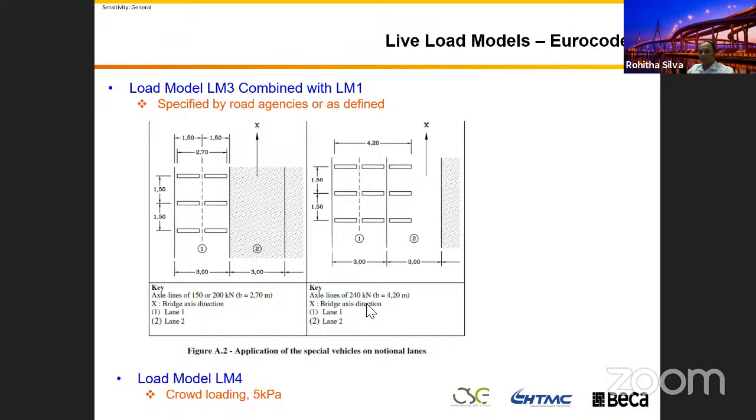If you go to higher axle weight or your vehicle width is 420, then you need to occupy two design lanes, because the width is 4.2. Two design imaginary lanes is 4.6. So normally in the bridge design, for example in Australia, we normally define the location of this heavy vehicle when we transport. So normally it's the center line of the carriageway. We just mark it in the bridge drawing. You will learn later.